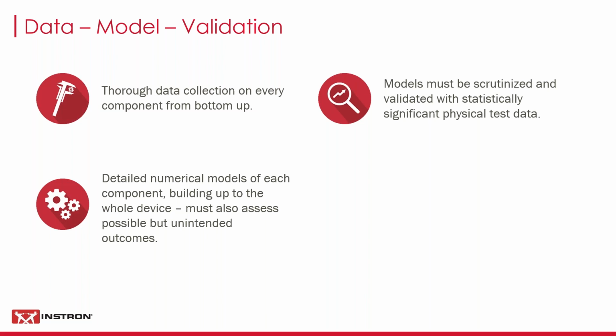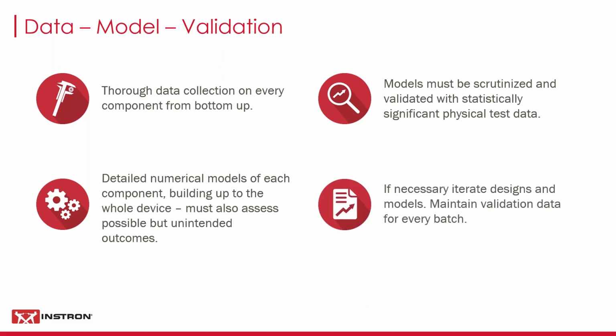It's quite challenging in terms of doing a representative test, but in vitro, so in an engineering sense, before we get to any clinical trials. Now, it's very important to iterate your designs based on what you see in the models, perhaps based on some of the outlying possibilities. And once you move forward into production, you have to keep maintaining that validation data. You have to keep checking the materials pedigree, the batch data every time you start a new batch of material, even if your structure design is unchanged.